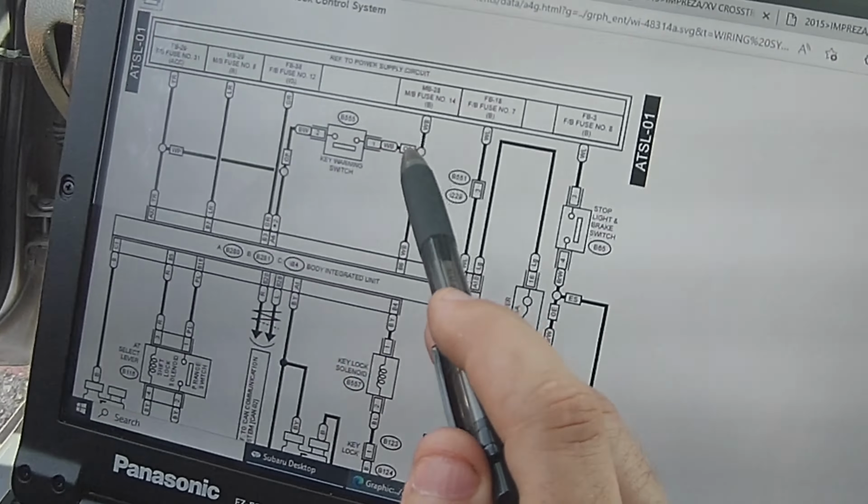Yeah, there's a ding. Okay, so I just get the regular dinging prompt when I power the vehicle up. Let's see what happens if I open the door with the key in it. I don't get anything. Okay, let's replace that fuse.